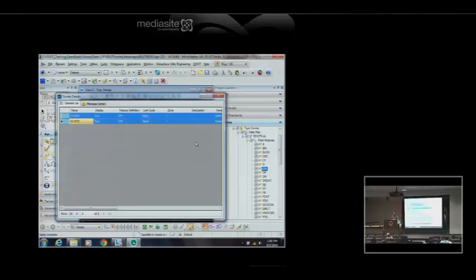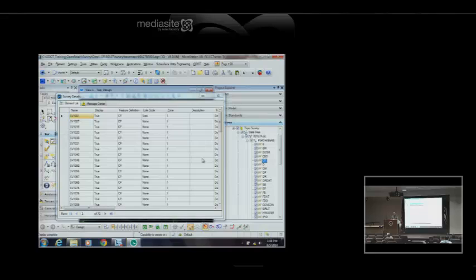If I pick a linear feature like center of pavement, see, these are all the shots that were coded with center of pavement. First one, its linking code was start a line. Next one, there's a linking code, so next keeps connecting until it either gets to an end or another start. So there's another start. They didn't actually code an ending point in this data set.